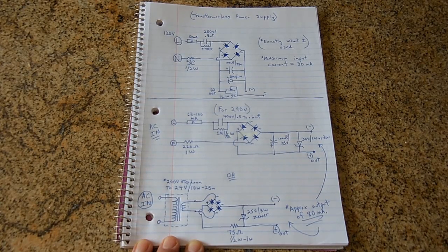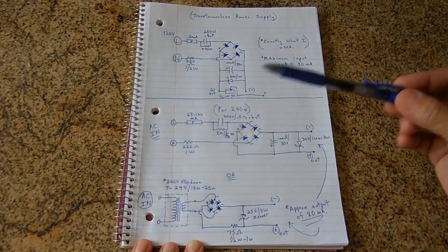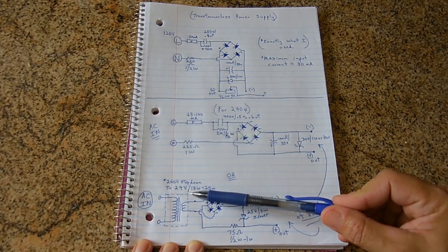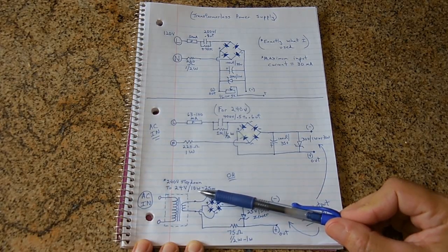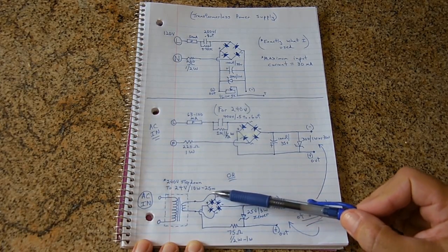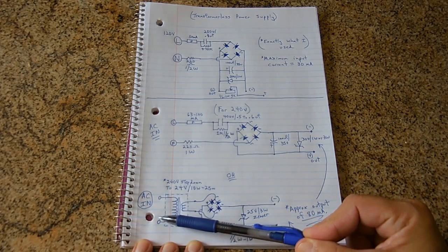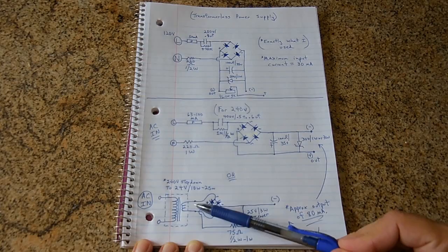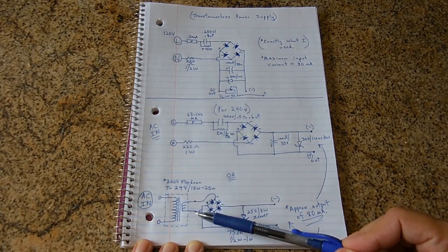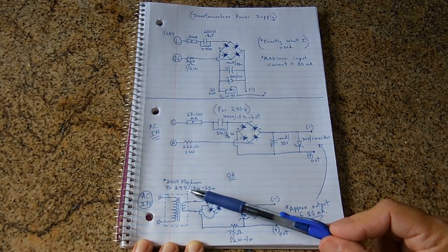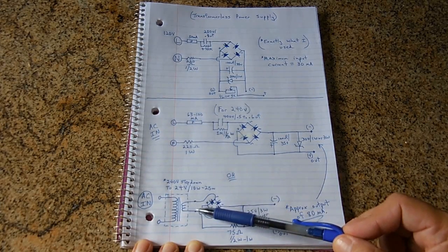Now if you're going to be using 240 volts, because the voltage is much higher, I would suggest, for safety reasons, that you use a 240 volt step down transformer to 24 volts, and I would keep it as close to 10 watts as you can. You can use up to a 25 watt if you would like. Over here you have your AC input, 240 volts. This is your lower voltage output of 24. When this is open circuit with nothing connected, that 24 volts will probably be around 32 volts.